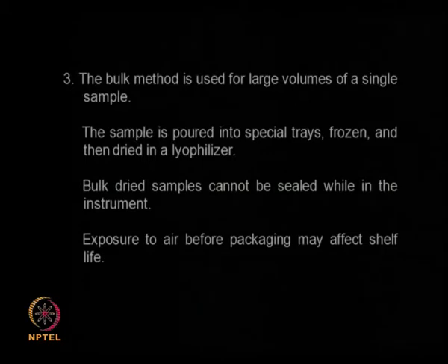So if you are talking about not exposing the material to the outside atmosphere, the best method is manifold drying or vial drying. So you take the samples in hundreds of vials, freeze them, connect them to a manifold, apply vacuum, slightly heat it up, so all the moisture is removed, and then you can seal the vials or flasks. So that is the advantage of that type of setup. Whereas in this type you can handle a large quantity of material, but some amount of exposure after lyophilization is inevitable here.